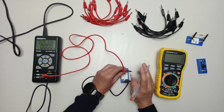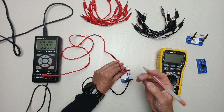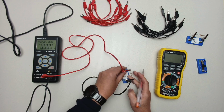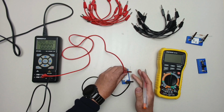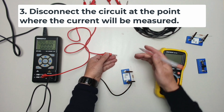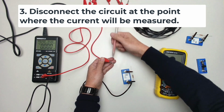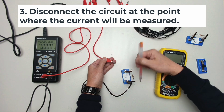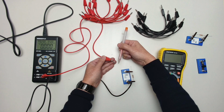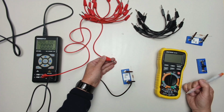And what next? This is important. If you think about it, we are going to measure current, so we have to plug the current or the water into our meter. It means if you want to measure current, you have to disconnect your circuit. Now, with the water analogy, the water is coming through here, but once it's disconnected from your device, this water will come out from this point. Now, how to measure the flow of the water? We plug this one into the meter.